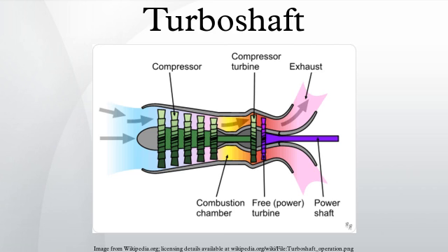An unusual example of the turboshaft principle is the Pratt & Whitney F135-PW-600 turbofan engine for the STOVL F-35B. In conventional mode it operates as a turbofan, but when powering the lift fan, it switches partially to turboshaft mode to send 29,000 horsepower forward through a shaft and partially to turbofan mode to continue to send thrust to the main engine's fan and rear nozzle.